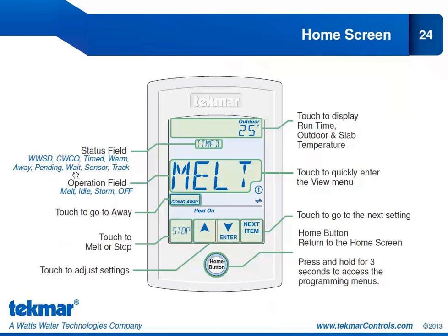We have the wait, and the wait would show up if we are waiting for that zone to operate due to your priority setting. We have sensor, and that would appear if you are using the Tandem snow ice detection function. And track, if this 654 is tracking the operating time of the zone that has the automatic snow ice sensor 090 or 094, then the word track would show up on the screen. So this status field is very helpful to tell you at a glance what is happening in this snow melt zone.